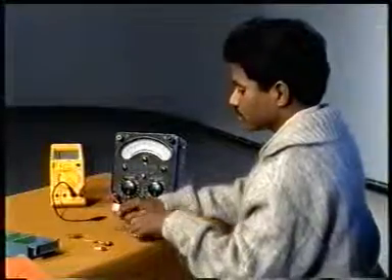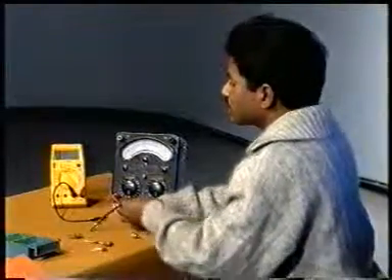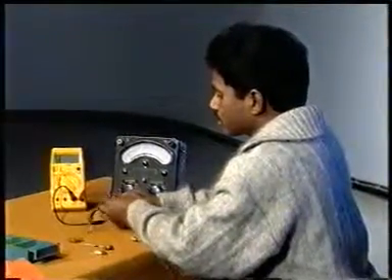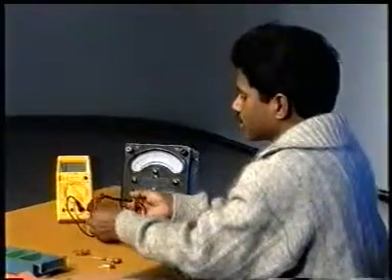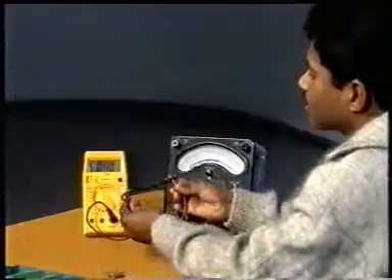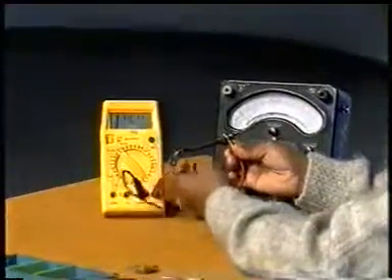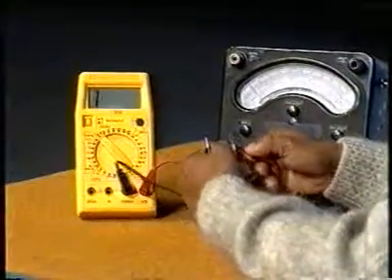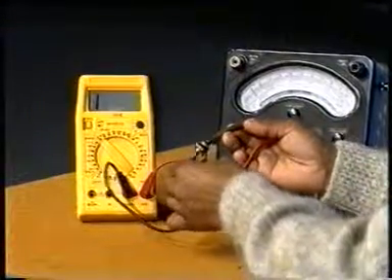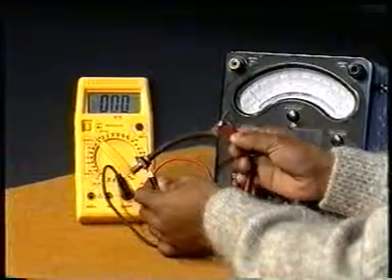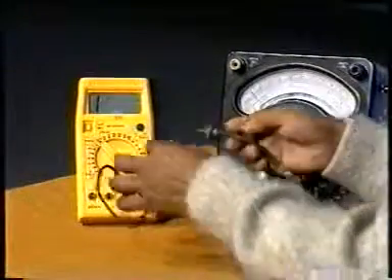We can check some of the damaged components also, damaged diodes say. He is going to test this power diode with the help of digital multimeter, and he is connecting it forward biased, and it is giving 0 resistance. What does it mean? It is a short diode. 0, so it means it is a short diode.